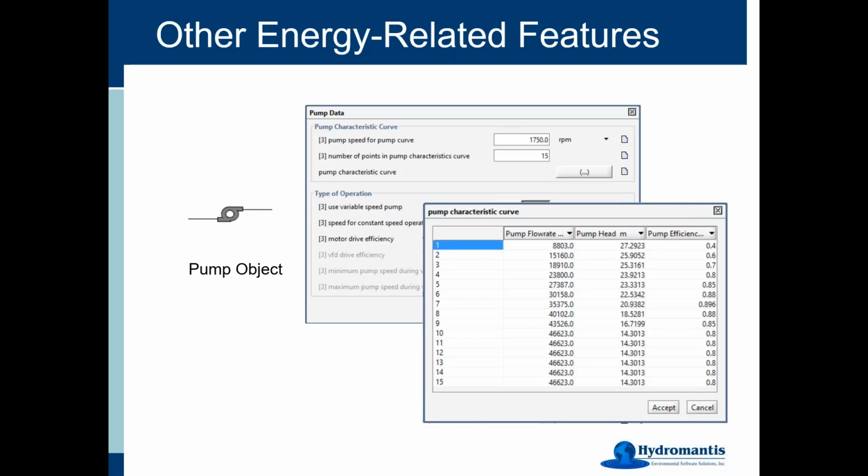We've assumed a very linear relationship and constant efficiency. If you would like to model the pumps in more detail with an actual proper pump characteristic curve and a system curve, you can do that in GPSX, but you have to put one of these objects into the system anywhere you want in the connection line as it moves from object to object.